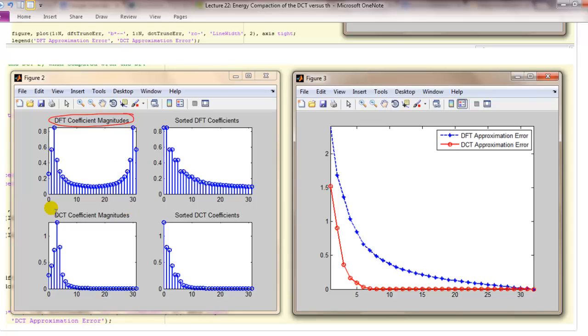When you look at the transform of any signal and you see this kind of a property, that is just an immediate way of seeing whether that transform does a good job of compressibility, or giving you a good k-term approximation, or does a good job of energy compaction. And you can see that for the DFT coefficients, they are not very close to 0. Okay, so these are the raw DFT coefficients. They are absolute values. I haven't changed the indices.